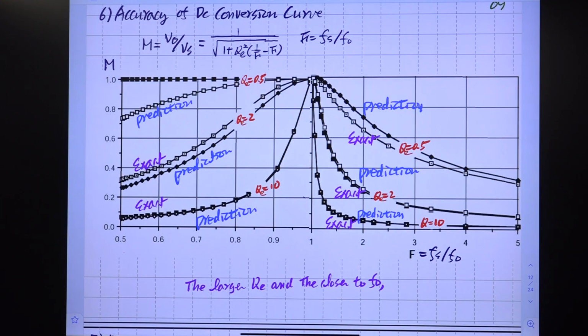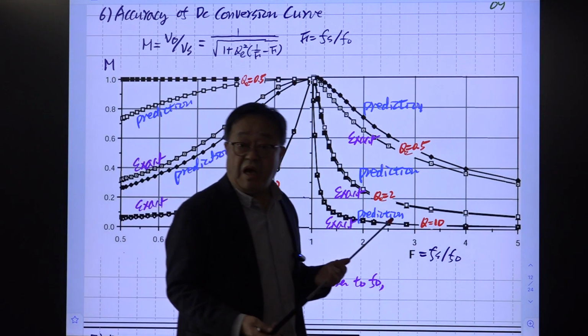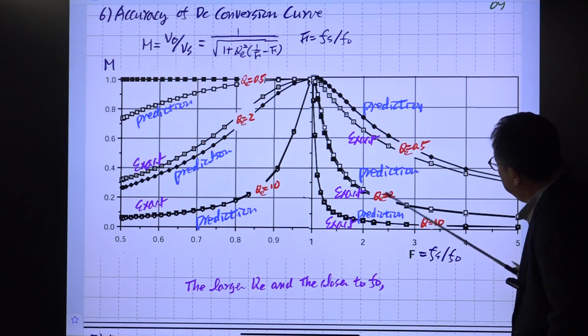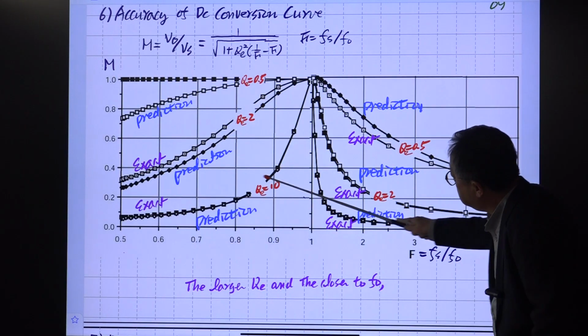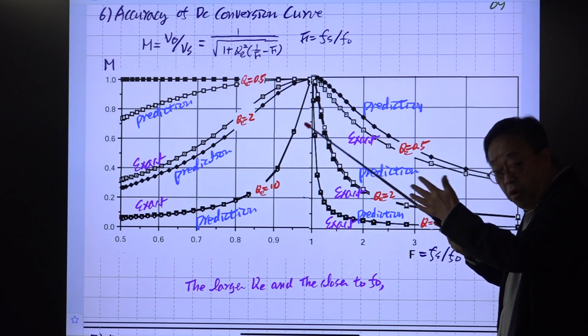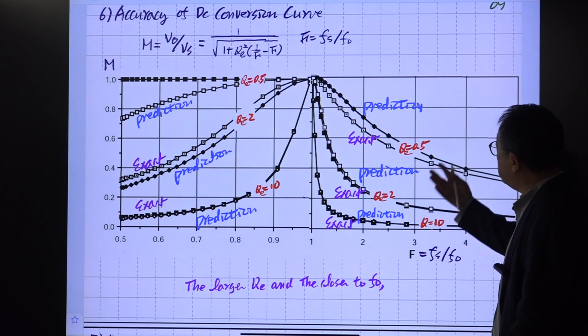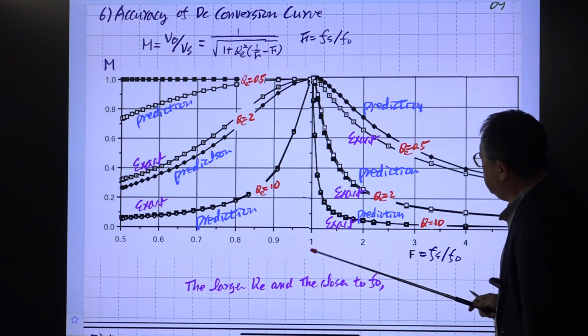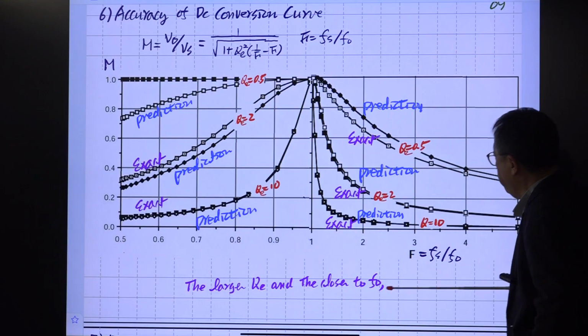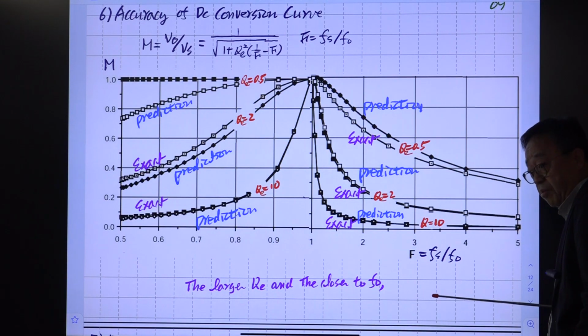He has that result. He used that result and compared the exact one with this approximate gain based on the sinusoidal approximation and the simulation result. So the accuracy is fairly good in this region with high Q. High Q is necessary to obtain accuracy of prediction of the sinusoidal analysis, and the larger the Q and the closer the switching frequency is to resonance, the better the accuracy.